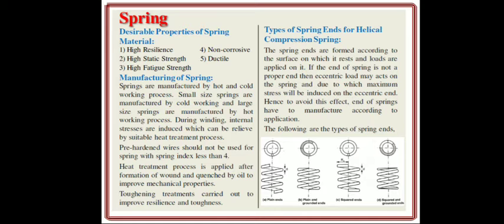The spring ends are formed according to the surface on which it rests and the loads applied on it. If the end of the spring is not proper, then an eccentric load may act on the spring, due to which the maximum stress will be induced at the eccentric end. Hence, to avoid this effect, the ends of the springs have to be manufactured according to the application. So as per the application, you can select the end type of the spring.